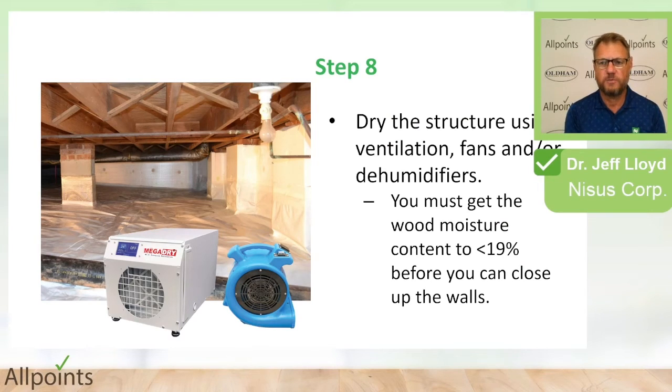Step 8 is to properly dry the structure. Now, if you've got electricity again, that's wonderful. You can run the HVAC, and if you've got ceiling fans and you can click the fan on the HVAC, that will do a slow job of drying the structure. And you don't have to dry it too fast because you don't want to cause wood shrinkage and other issues with over drying a structure.